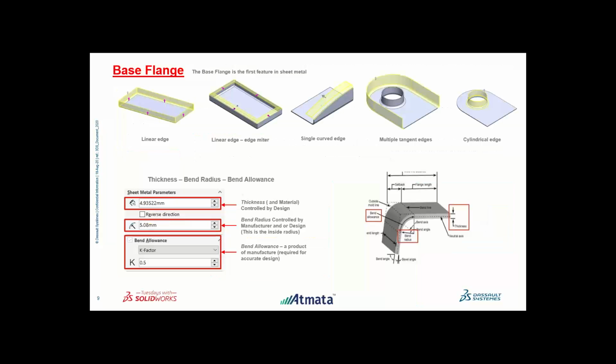Every sheet metal design starts with a base flange. What you see here, the completed one, is actually a base flange. On the base flange, you can start creating edge flanges. We see here different kinds of flanges. All these edge flanges are based on a base flange.